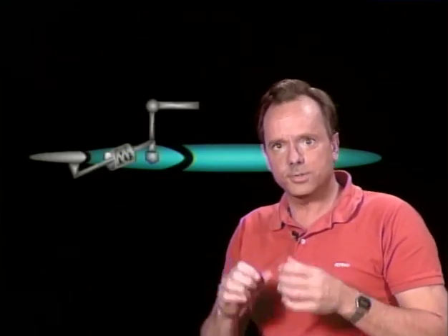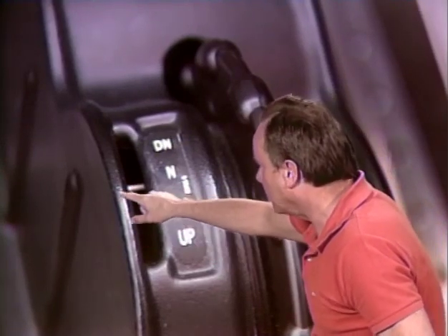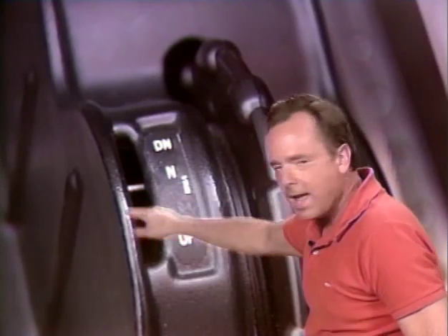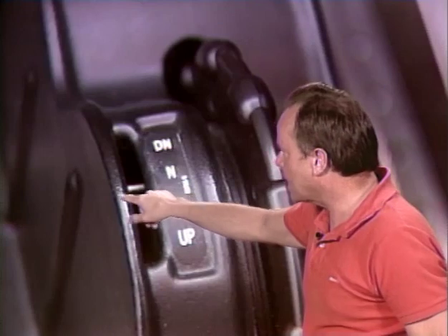Now they want you to know that when you're inside the cockpit and you have flight control trim systems, the controls inside the cockpit must be designed and installed so the pilot can determine the relative position of the trim tab from the cockpit. So that's an important thing, and it's got to be accurate, as you might know. If you install a trim control inside the cockpit, the pilot must be able to see the trim position from inside the cockpit.